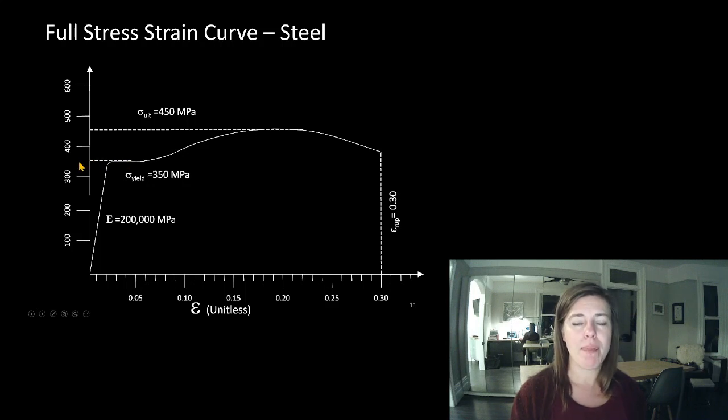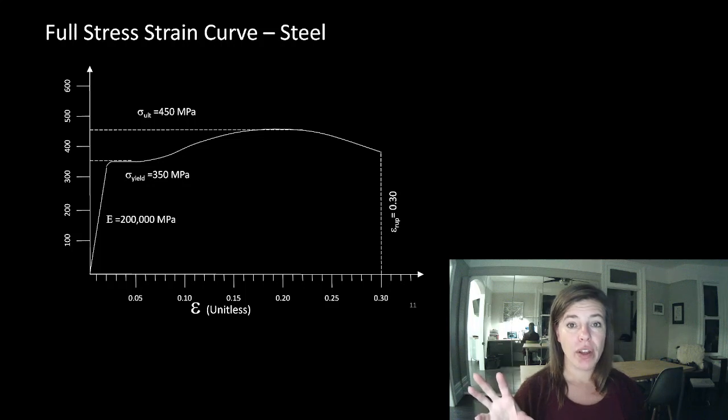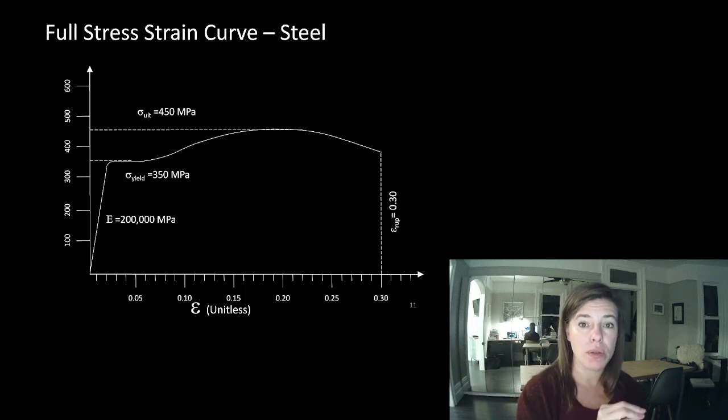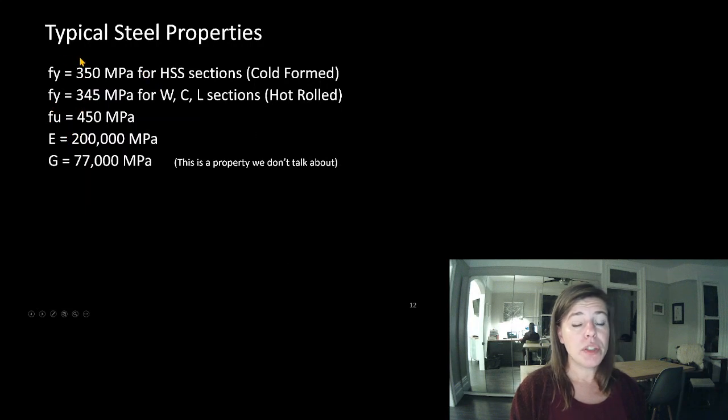Remember, if we want to know the capacity of our steel, yeah, great. All along here works. We're good. We could test all of this and we know that we're okay. But what we want to make sure is that we don't go past the maximum stress on our steel. Doesn't mean we want to hit that stress, but we know that that's the maximum stress. So if we make sure something at the verge of failure is still okay to support the loads, we know anything below that will still work just fine. So we usually use our FY to verify that we're okay.